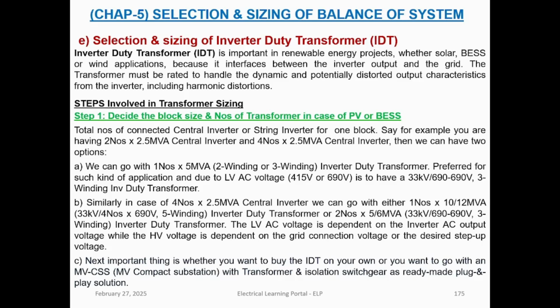Okay, great. So moving on with the next topic, that is if you prepare an SLD or a configuration, like if I have to just draw it here, then we understood things related to battery first, right? So there was a battery container, probably multiple battery containers containing different megawatt hour, kilowatt hour storage of battery, which are connected to the DC side of the inverter, right?